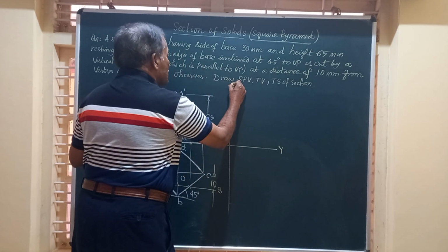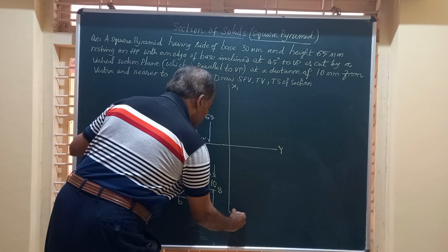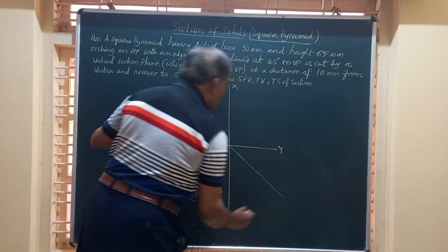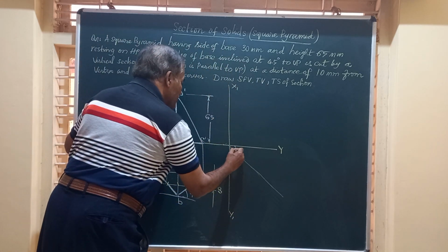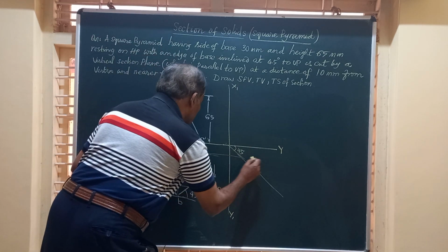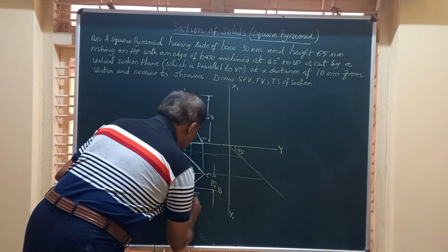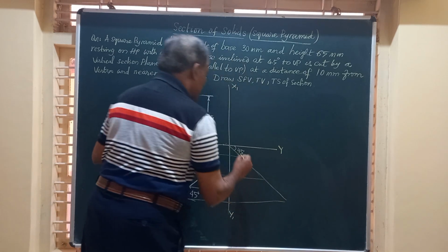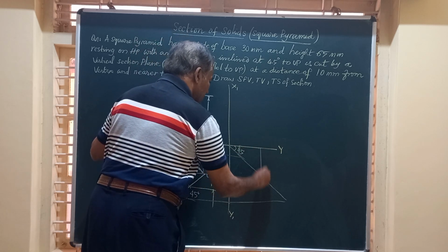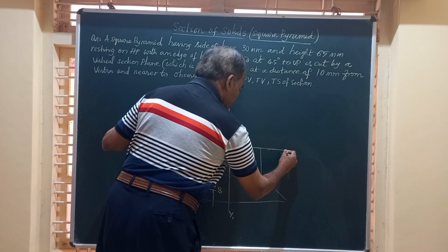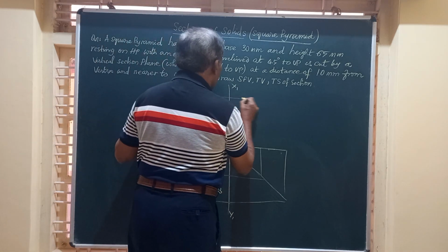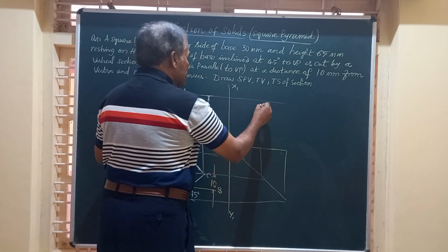the end view by drawing a line x1, y1 parallel to that, and here I obtain the side view of this. This will be at an angle of 45 degree to obtain the side view. Friends, I transfer all these lines and obtain the end view. So friends, here you will have point 1, this is second, and this is going to be third. And whatever the view we are going to get here will be just identical to the one we have got in the front view.